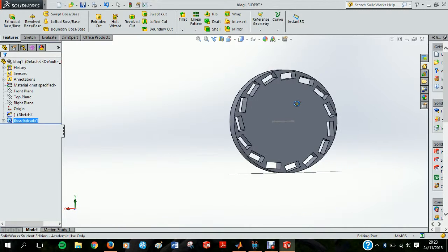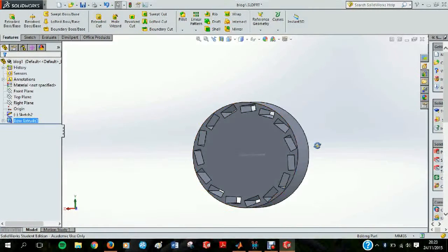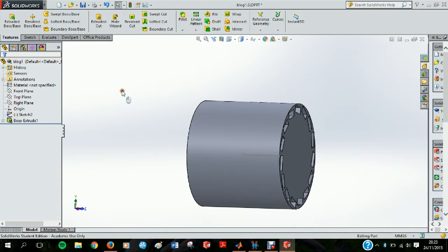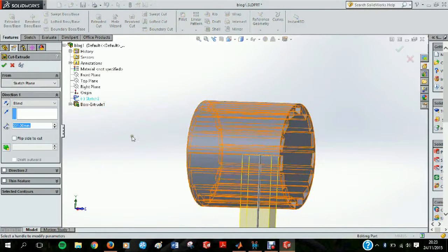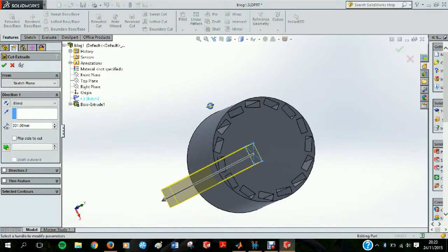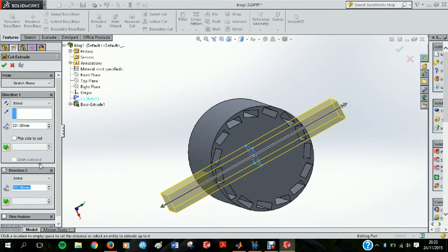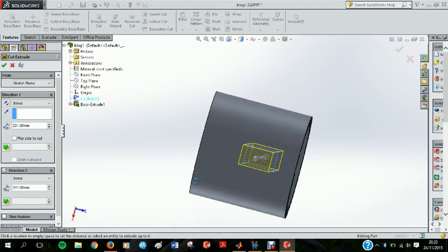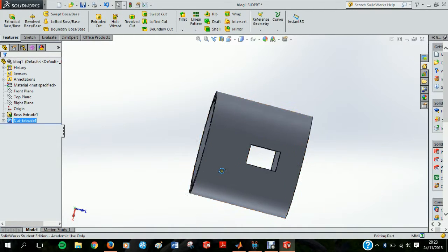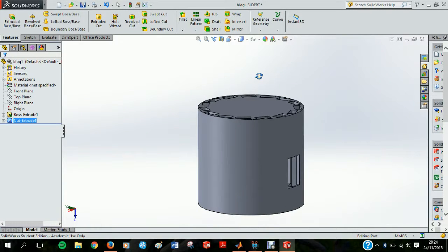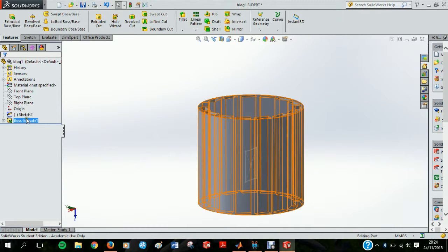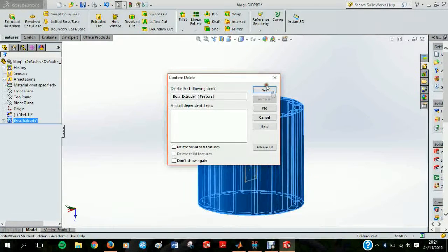Here we can see how the drum, or the linear pattern or the circular pattern we created, can be solidified into a 3D object, very simply, using very simple functions. SOLIDWORKS is a great software to gain an understanding of how 3D objects can be created. There's also another function, the extruded cut function, where we can cut our top view square. We can make a slot straight through. And we're going to clear our whole workspace by deleting each part systematically.